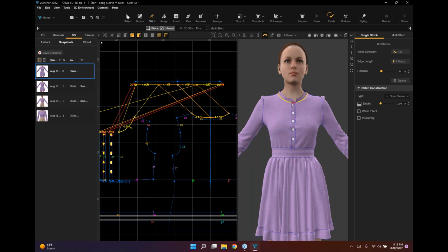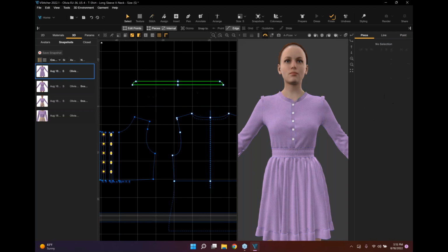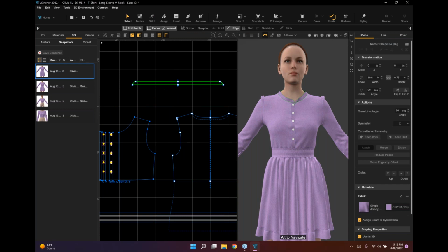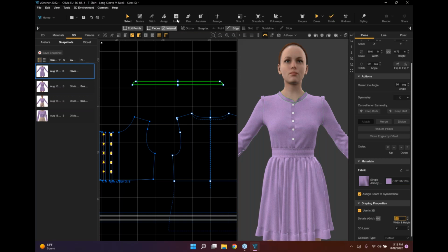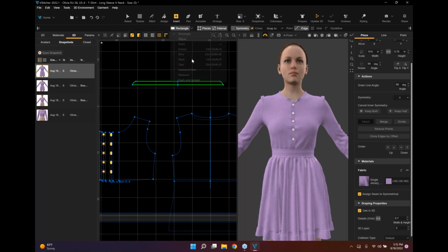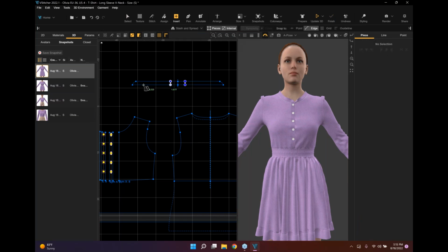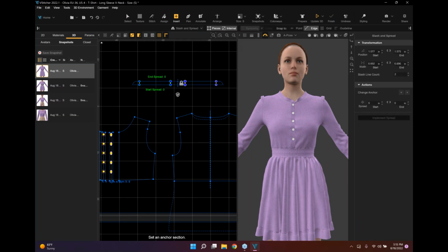So you might notice that it's kind of at the top edge, and you can decrease the top edge width with some slash and spread. I'm going to update the grid of this so it's not at 1. Then I'm going to use the slash and spread. So from my drop down, select slash and spread, do the same thing here. Add 5 slash lines and then maybe close it by just 1/8.